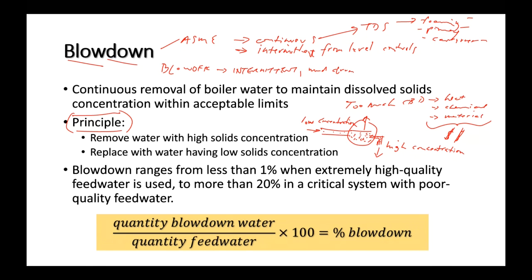And then when I got into power engineering and I'm learning about dissolved solids in the boiler, I went, oh, that's the same principle. So you should know that the only way we can reduce dissolved solids is to get rid of the stuff with high solids and replace it with low solids. We can't miraculously make the solids disappear.